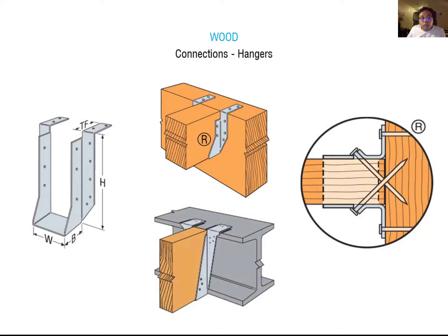So also understanding how you can connect the timber structure to the timber structure. We usually use this hanger. This kind of hanger, you can see. This hanger simply connects to the beam, and then when you have the joist here, you can just use this hanger to connect to this joist. It also works in metal structure or any type of concrete structure as well.